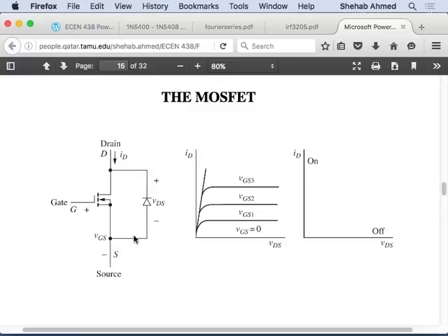Right? So, yes, sir. Is the diode positive also? Yeah. With the MOSFET, it's part of the structure of the MOSFET. It's internal. It's called the parasitic diode. If you go back to 325 material, you'll find one section about the parasitic diode. I don't know if Dr. Bina covered it when you were teaching it. But it's there in the model, right? But in power electronics, I don't utilize it that way because I cannot control anything that way. If I flip the voltage polarity, it's useless.